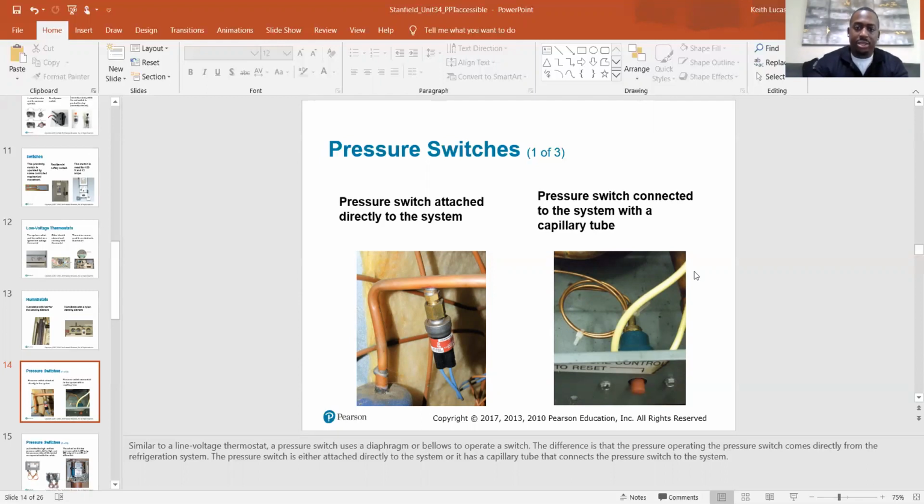So if you do find yourself having to reset your pressure switch, you're gonna want to throw your gauges on there, check the pressures, and watch how the system performs, because something caused it to trip and it'll probably trip again. But I've also had faulty switches that were tripping for no reason at all. And I had to bypass them. I didn't just bypass it irresponsibly and not check the system. I ran the system for like an hour, just kept doing all my simple little checks.